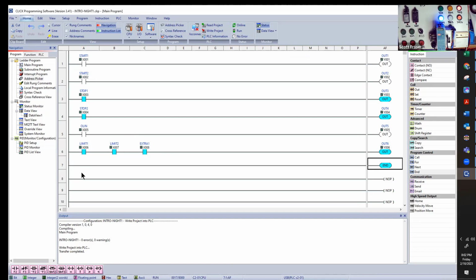But essentially what I want to do right now is go through here, push start 1, and I see Y1 going on and off. X2, okay, I see Y2 toggling, okay? So when I push it, the light turns on. Now in this case, since it's normally closed, it's already on, so I'll push it, and the output's going to turn off. Same here.